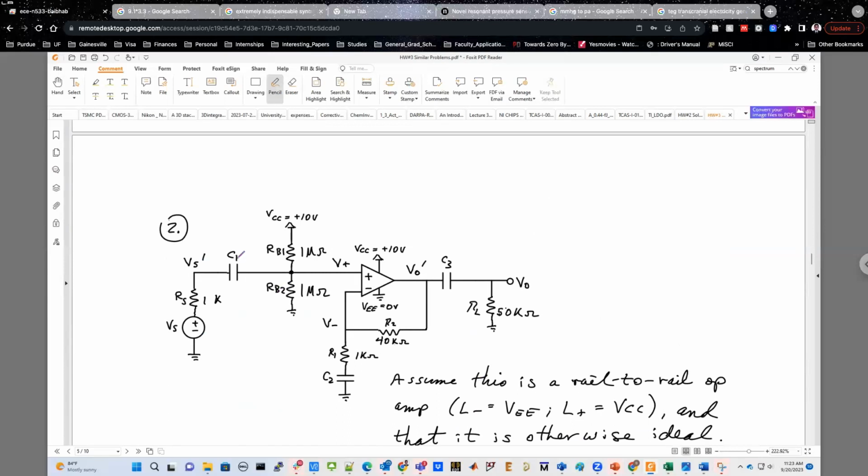As you see, at the input side, you are seeing a new network right now. You're seeing something like this. At the output side also, you see something like that. And then there is a capacitance and resistance which is connected over here. So there are 3 different RC networks already connected to the input or output of this circuit, which you have not seen before, right? And why are these capacitances and resistances there? These are present because of something that we have talked about before, but haven't talked about in detail. That is called biasing the op-amp, or DC biasing the op-amp.